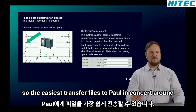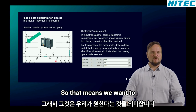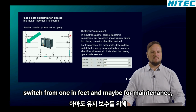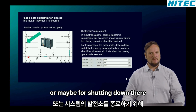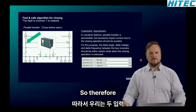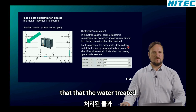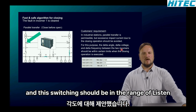So the easiest transfer is the paralleling transfer, because we have idle conditions. That means we want to switch from one in-feed to the other in-feed, maybe for maintenance, or maybe for shutting down the power plant or the system. For this purpose, we use the delta angle, the delta voltage, and the delta frequency between the two incomers.